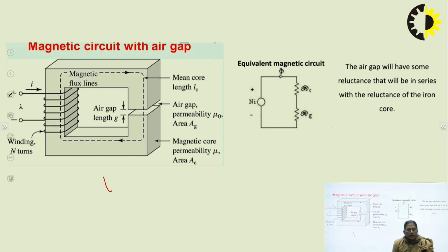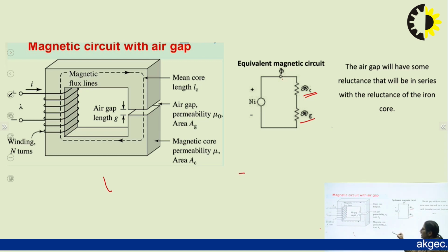So I'm having two reluctances. One is by the air gap and another reluctance is with the core material, right? But both of these are experiencing the same flux. So this is an example of a simple series circuit. If at all I want to have its electrical equivalent,